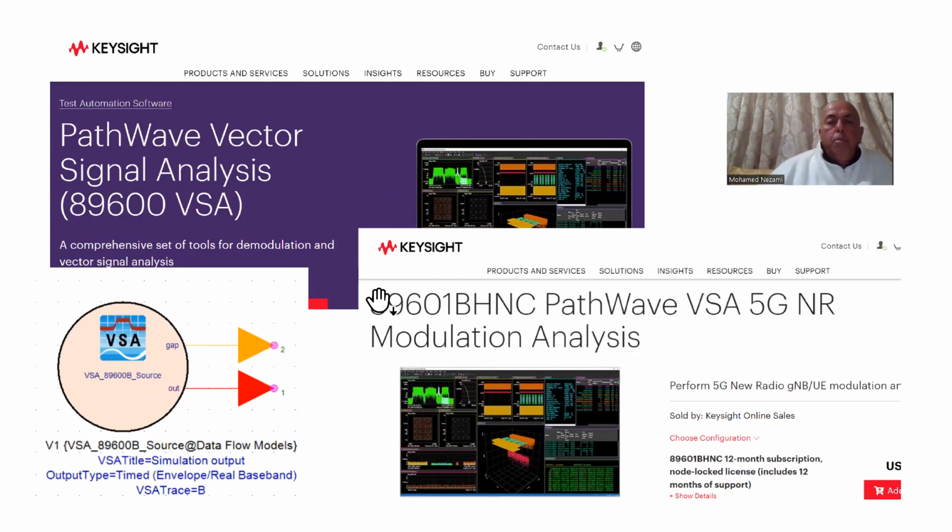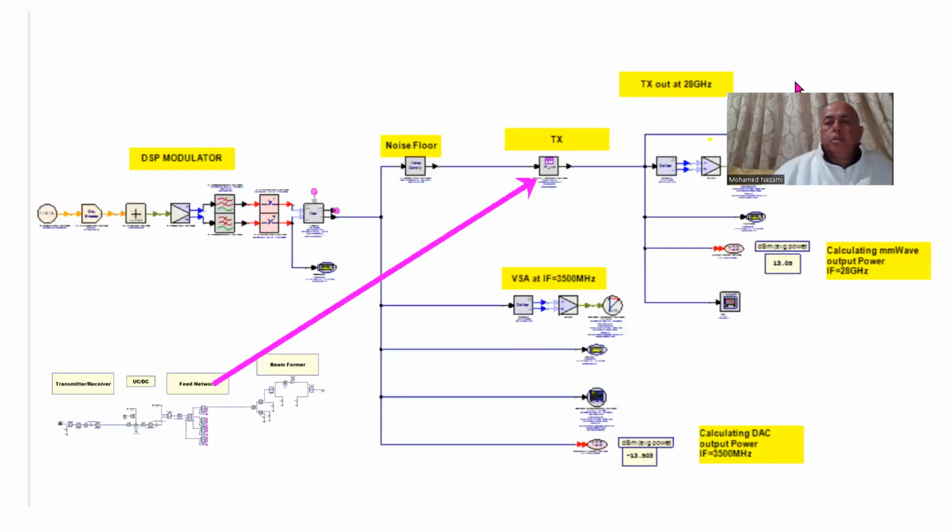But I'm going to run the built-in demodulator from PathWave, and that's good enough because it shows me very much the same things. Okay. Also, they have another function in here, which is the 89601, which is entirely for VSA 5G modulation analysis, so you could utilize this one as well. I don't have licenses for these two separate systems.